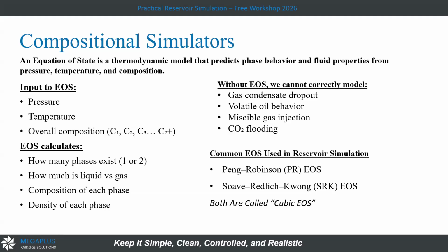If, as an example, the fluid is very thick, or a very heavy oil, we will try steam injection. If the water mobility is higher than the oil, we will add a polymer to the water, so we can alter the physical properties of the water and increase the viscosity of the water, so it will improve the micro sweeping,